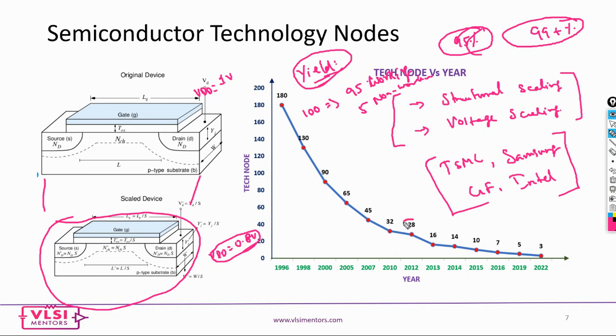So for example, 28 nanometer is still a good yield node, and 16 is again a good yield node, and 7 is again a good yield node, but somehow in between, 14 and 10 are not great yield technologies. If you check, nobody is using regular 10 nanometer because it is a bad technology where the yield was less than 30%. So the whole industry has abandoned the 10 nanometer.